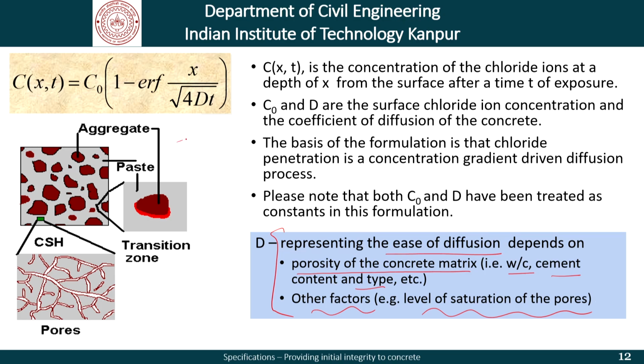So, what is really shown here is a schematic of the concrete, that we have these coarse aggregates in mortar, and if we take a small part here, what we see is this HCP, that is hardened cement paste, and this is the pore structure. So, this pore structure could be coarse or fine depending on the kind of hydration that we have had, the strength of concrete and so on.